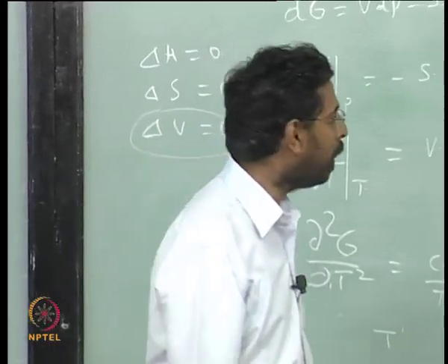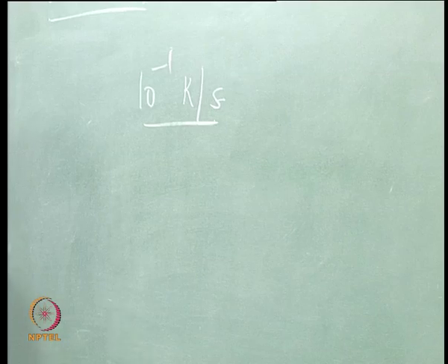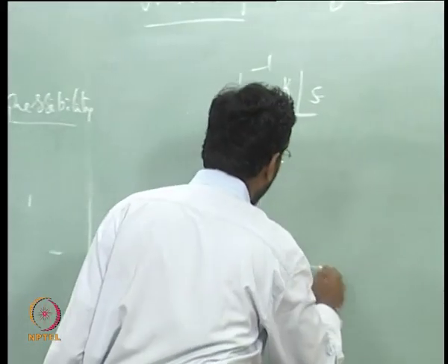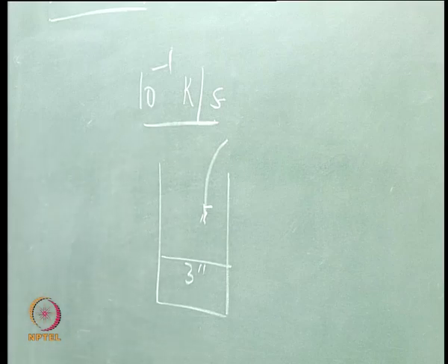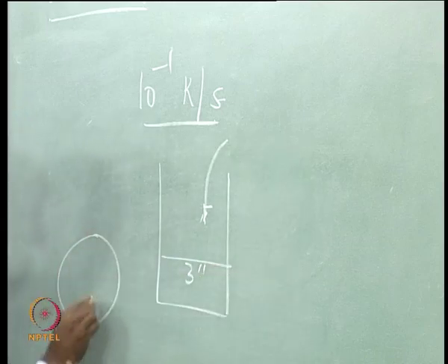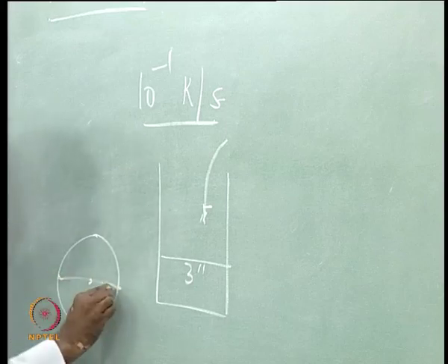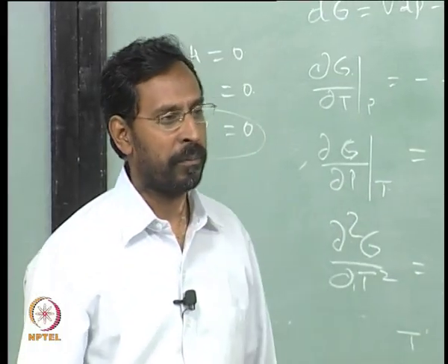So, what people have simply done is they have taken liquids of such glassy compositions and poured them into a mold of almost 3-inch thickness, and then cut this cross section and looked at it in the microscope, and they saw that throughout this cross section, from the center to the surface, it is all glass. It is almost similar to your hardenability parameter.